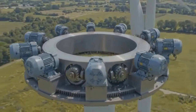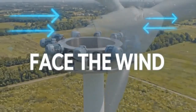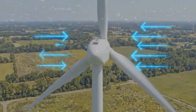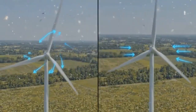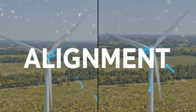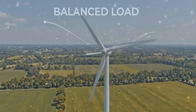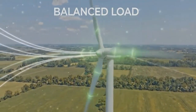The pitch system is not controlled by hand. It is automatically managed using sensors and operating data. Sensors on top of the nacelle measure wind speed and wind direction, then send that data to the controller. The controller analyzes wind speed, rotor speed, generator load, and blade pitch angle before choosing the right adjustment.